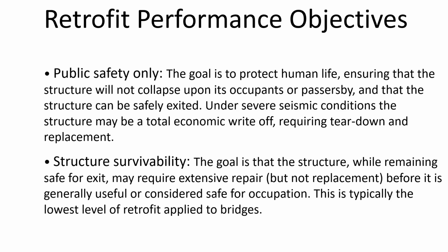Retrofit performance objectives. Public safety only. The goal is to protect human life, ensuring that the structure will not collapse upon its occupants or passersby, and that the structure can be safely exited. Under severe seismic condition, the structure may be a total economic write-off, requiring tear down and replacement.